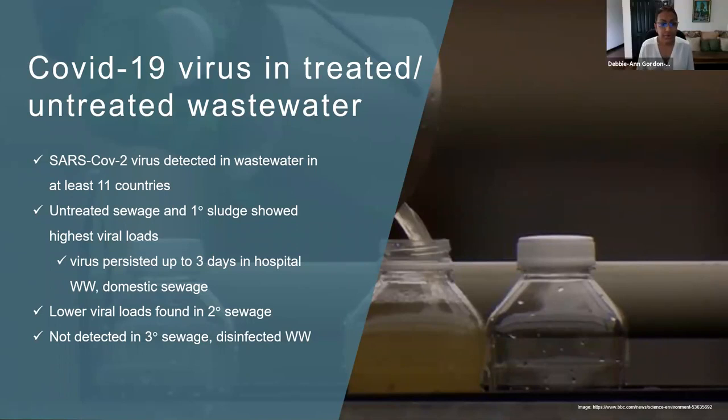None of the studies found or detected the virus in tertiary treated sewage and disinfected wastewater. And when I talk about disinfection, I'm talking here about chlorination or addition of peracetic acid. So although we cannot say that treatment is 100% effective, there is certainly evidence that supports a significant drop in the viral loads in wastewater following various stages of treatment.